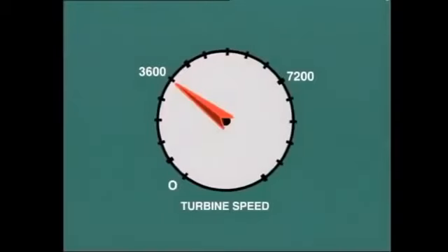In this case, steam flow to the turbine would continue, with the result that the speed would rapidly rise to 2 or 3 times normal. In practice, the speed would not get that far, because centrifugal force acting on the mechanical parts of the turbine and generator rotor would cause them to break up. Several instances have been reported of turbine blades and sectors of turbine wheels passing right through the turbine shell into the turbine room, with the potential for injury to plant staff and damage to other equipment.